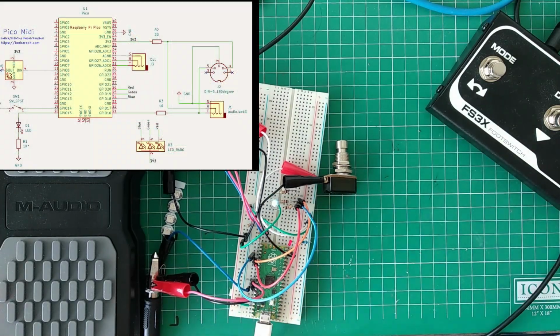Right, I hope this is visible. So, this is a clear diode LED. One thing to be wary about is that blue and green might need over 3 volts. They typically have 3.2, and we're driving them from 3.3 volts.